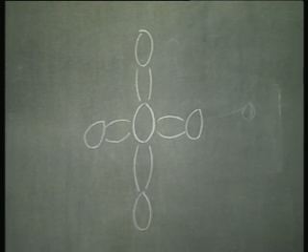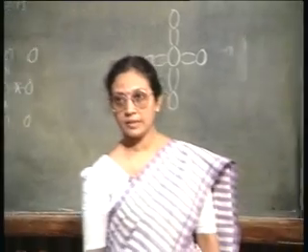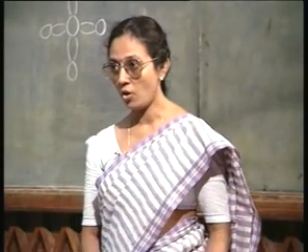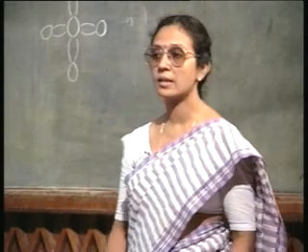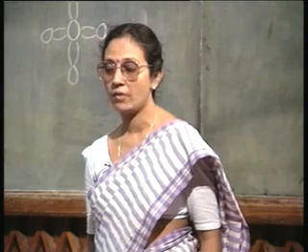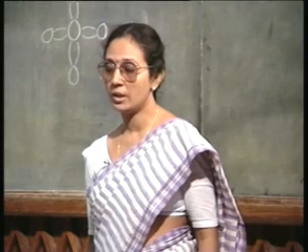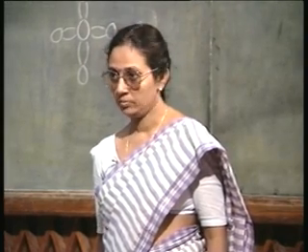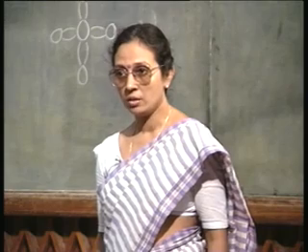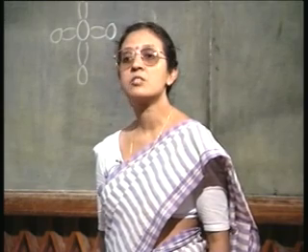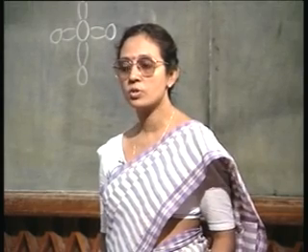And if I have a trivalent or a pentavalent atom, then I will have one hole or one excess electron. So, if I have an excess electron, as is the case of a pentavalent atom, I will have a donor. If I have a trivalent atom, then I have a loss of electron or a hole. So, then I have an acceptor. For such an electronically active impurity, it is very easy to understand that it must replace a silicon in the lattice site. In other words, it must be a substitutional impurity.